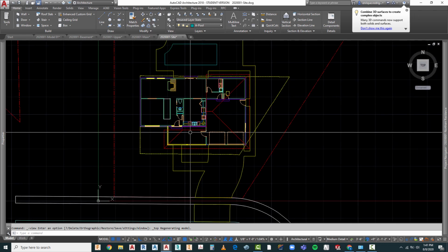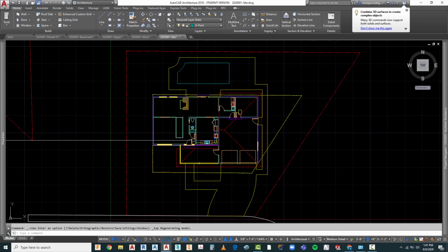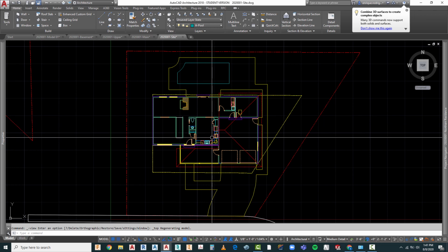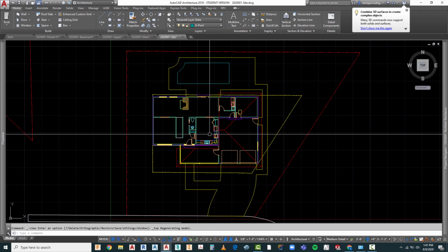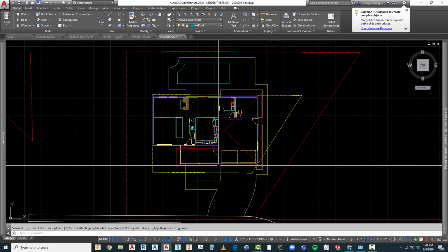In fact, that's a very common way of presenting, where you would have an overall site plan at a specific scale, which may be 1/8 of an inch, and then you can come in later on and you have drawings where you will begin to do what we call enlarged plans, so that you can take a look at a little bit more detail and dimensions on what you want to do.